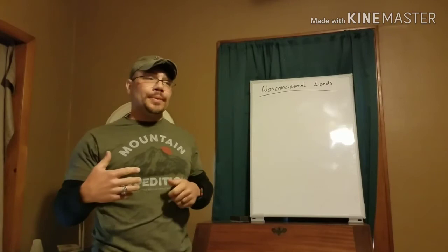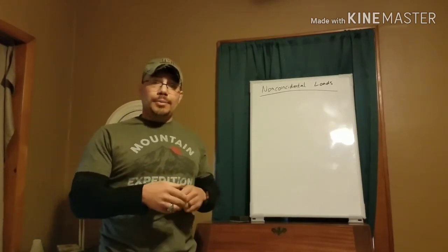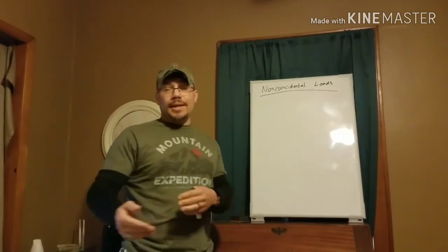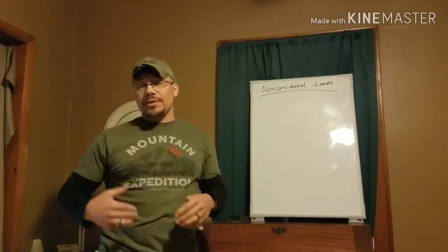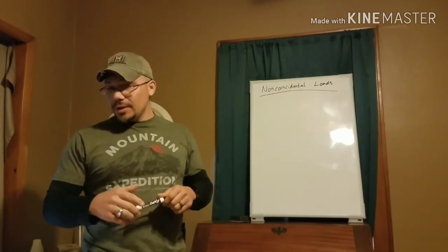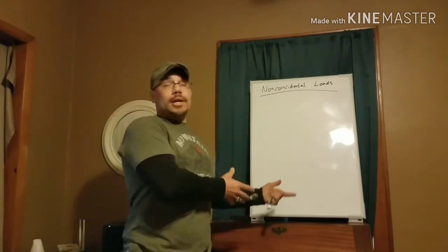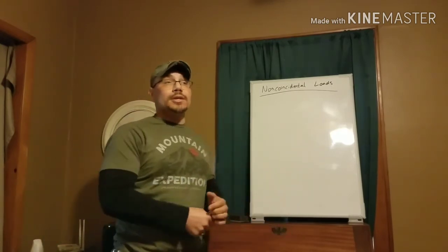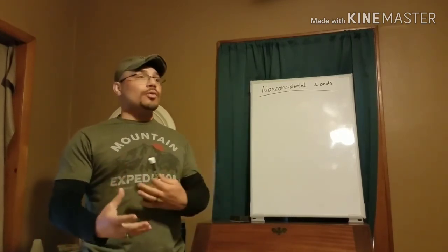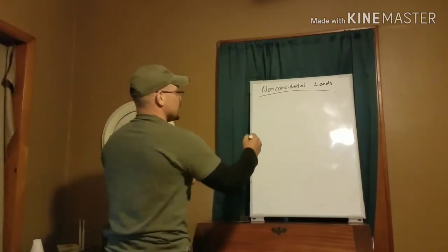Now, the only caveat to that is if you have a heat pump, right? Because your heat pump is going to be running both when the furnace is running and the AC is running, right? And so then we have to take that heat pump itself factored into the actual furnace load, right? We do know that if we have a heat pump, we need to add that in, right, to our furnace because it does run at the same time. So, but just to make things easier, we're going to say our total furnace load and our heat pump load or whatever is going to be 15,000 VAs.